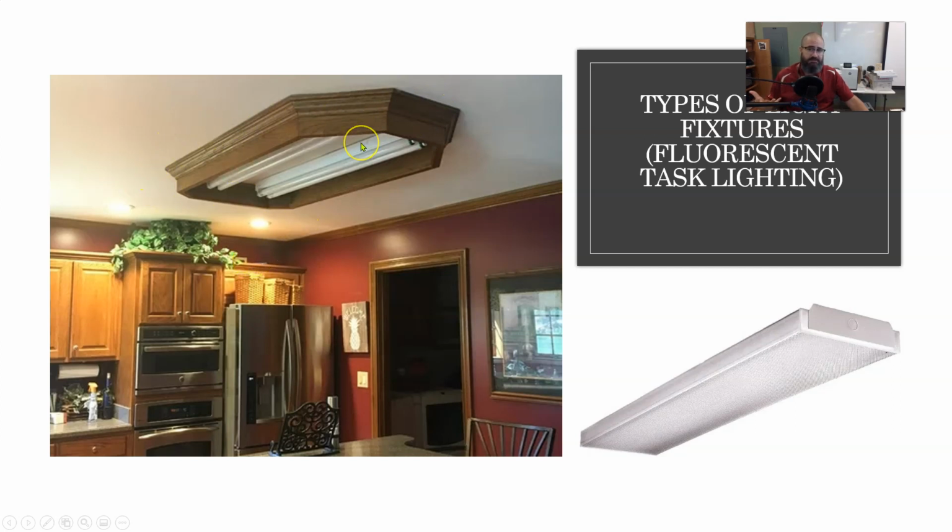Okay, so they have the fluorescent, the overall light, and then they have the task focused lights over on the sides, and they're controllable with different switches. And that's one of the things I was going to get to with kitchens and living rooms: in most cases, you're going to want to calculate both the low wattage calculation and then the high wattage. That was the 1.5 and the 2.5 multiplier. And have each one of those calculations controlled by different switches.